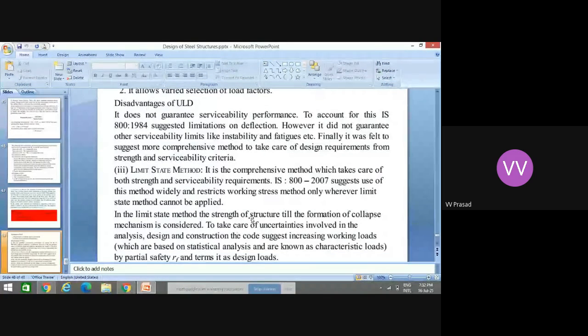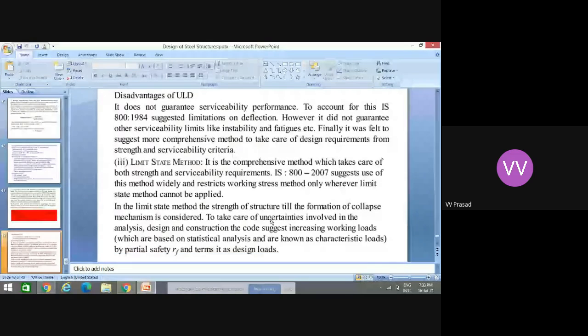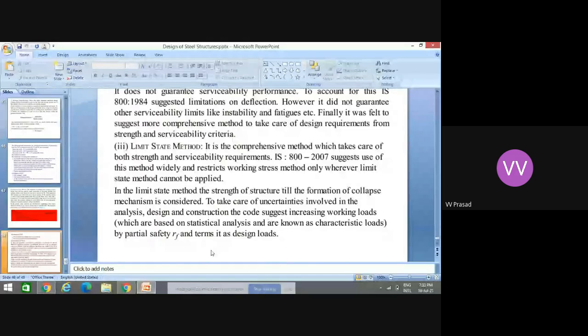I already told, in limit state design, load factors and partial safety factors for materials are applicable. Load factor of 1.5 is to be taken. So 1.5 is applied to the loads, bending moments and shear force, and partial safety factors are also applicable to the loads, shear force and bending moment. Generally, we have to select the steel section, either channel section, I section or T section, from the steel tables based on the area of the section.